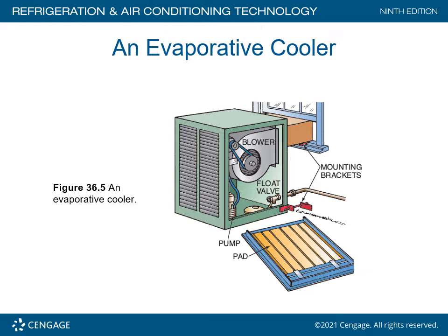You would put a T, and you would put a 1/4 inch line, like a dripper line, off of this T, off this discharge line, and take it down to your plants down below. By doing that, you're going to take what they call the TDS, the total dissolved solids, and remove that out of the water stream and put it in the flower bed, and basically double the life expectancy of the swamper as you see it.